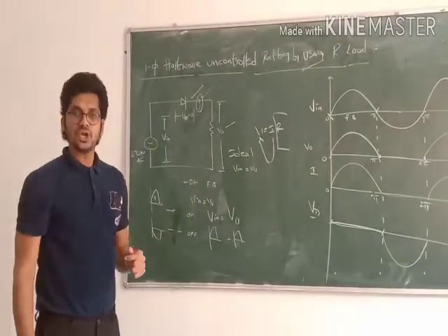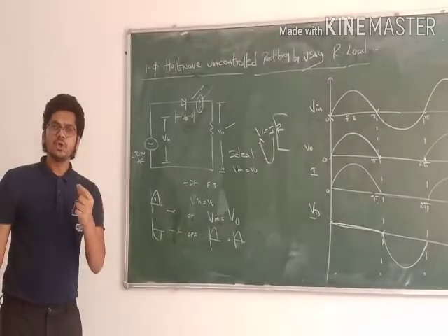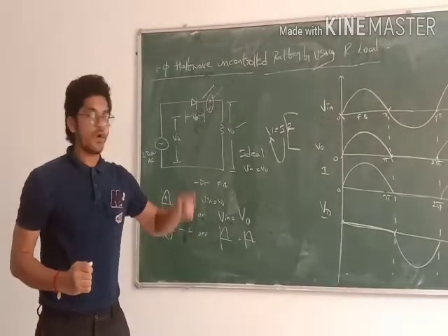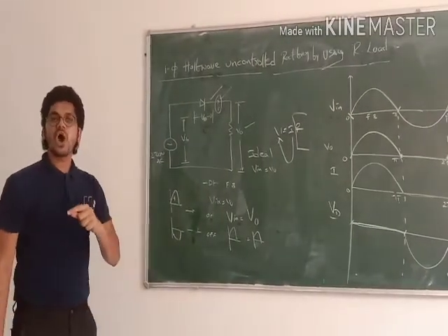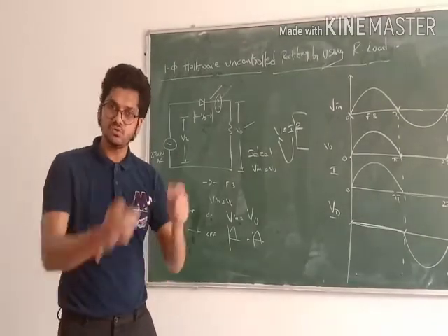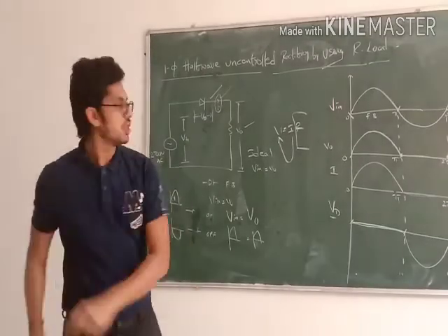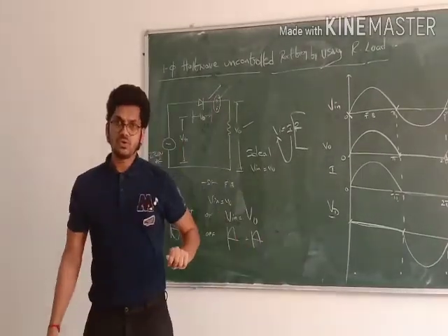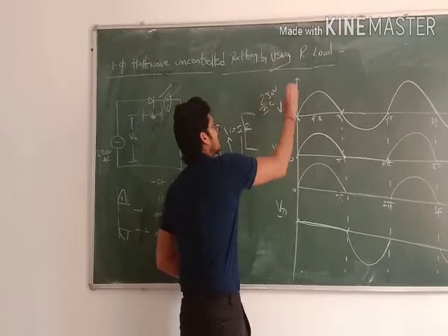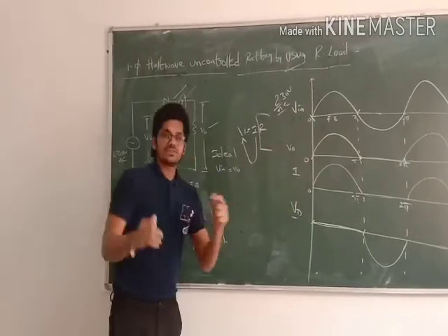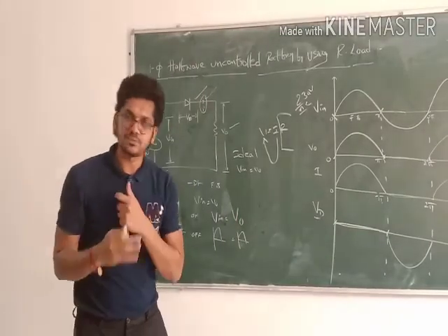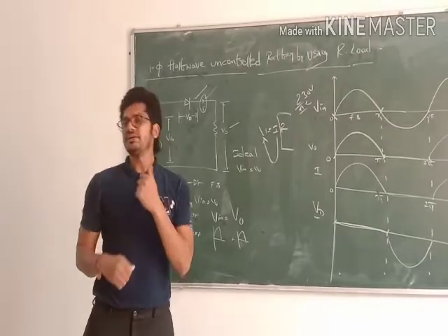So from this circuit, we understand that by using the shortcuts, meaning all the switches are ideal, and the concept of blocking voltages, we found the waveform of the single phase half wave uncontrolled rectifier. If you want to do it practically, take the breadboard, put the AC supply of 230 volts from the supply, put the diode, take the resistor, and you can get the same waveform on the CRO. You can measure the output voltage also. If I am giving 230 volts AC, you might ask, sir, where is the DC here? It is also not a pure DC. That is the concept of harmonics. We will discuss it later.